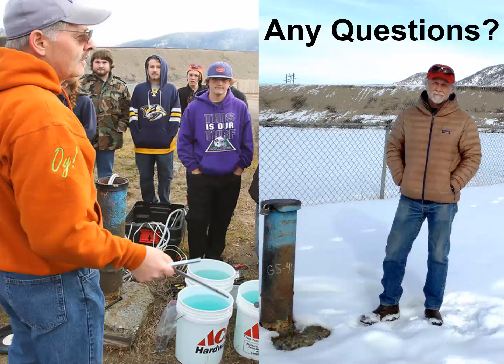The trouble with the aquifer is that you had contaminated groundwater, especially this middle alluvial unit at roughly 40 to 60 feet in depth, poorly defined, but there's a lot of fine-grained portions to that middle alluvial unit. And it is that groundwater, with dissolved copper, say, moving through that aquifer, and it's starting to load up those sediments.